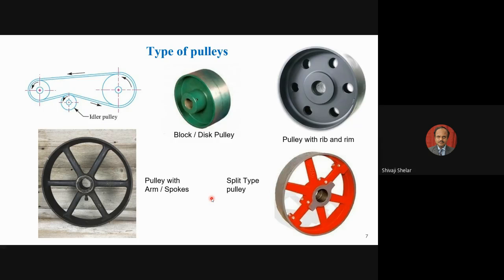So there are two types of materials used for the belt having a different density. Polyurethane material is used having varying density values. Again, number of plies, this is very important. Now you may ask, so what is meant by ply? Ply means you are taking a fabric material for the manufacturing of belt. Then number of such fabrics are taken. Layer by layer fabrics are mounted together, and the required thickness is obtained.